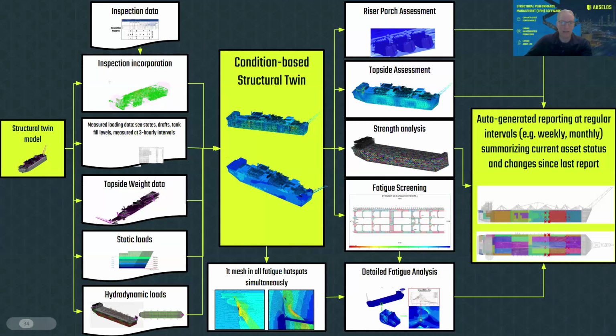Configuring all the static loads, like the different ballast and cargo loads, hydrodynamic loads, which is the wave loads, and meshing of all the hotspots. So with fatigue hotspots, there's industry standards about how you do the meshing. So we have T by T meshing at the fatigue hotspots, all in one model, which is unheard of.